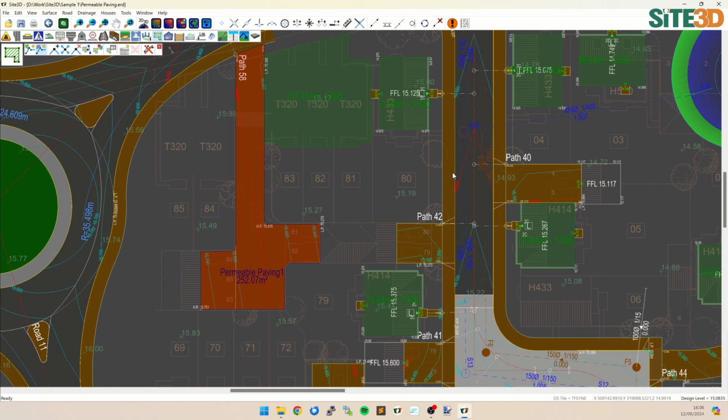The next thing it's waiting for us to do is select which node or which manhole that will be assigned to. So it assigns it to a manhole, not a conduit. We can say S13, click that one, and you can see the link will show you that it's connected to that one here via this blue arrow.